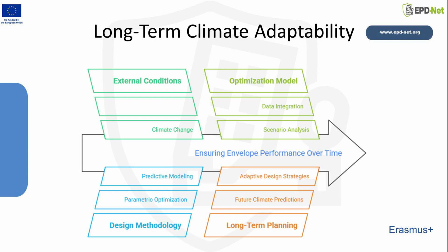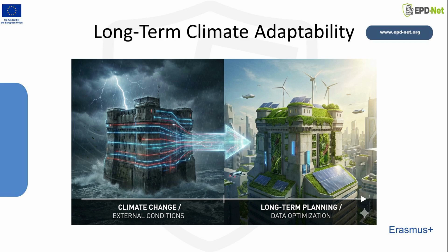A significant challenge addressed by parametric optimization is ensuring the envelope remains high-performing even as external conditions change. An envelope solution optimized only for current conditions will not remain optimal over time, particularly as global warming may expand the length of the shading period required. Parametric methodology incorporates this by allowing the designer to predict and incorporate likely changes to external influences into the optimization model, e.g., climate predictions for 2020 to 2080 scenarios, which yields better long-term results than a design optimized solely for current conditions.